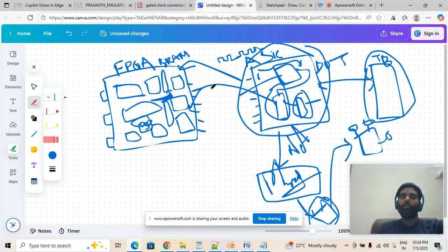I don't want to touch my RTL, but I want my tool to understand what it is up to. I have to provide some alternative solution, an alternative way of replacing these IPs. Any intermediate solution I can provide, for the tool to understand this information and start processing it. And finally, it will generate the netlist file for you. And then again, you go for the backend implementation.